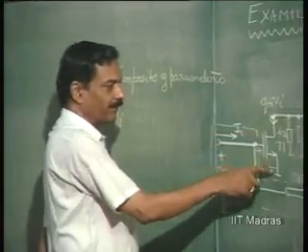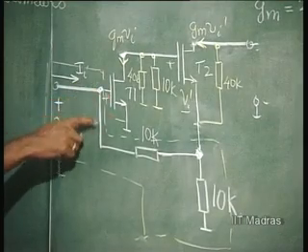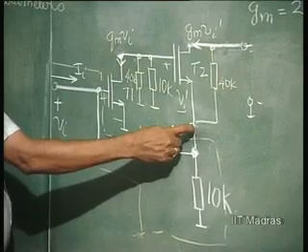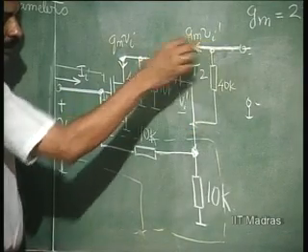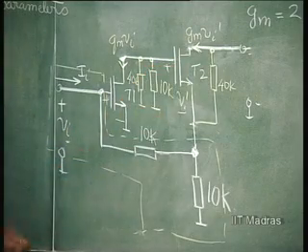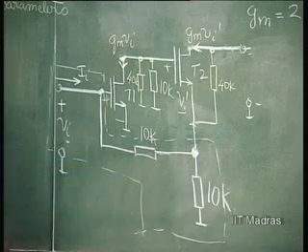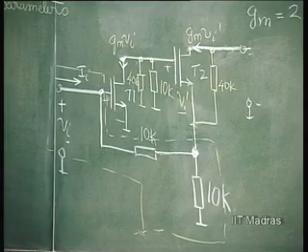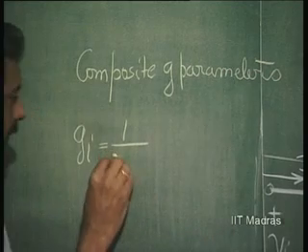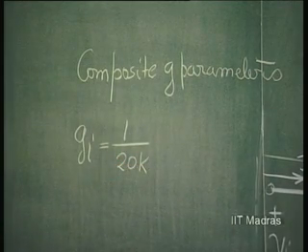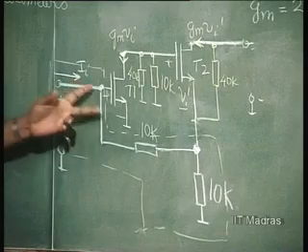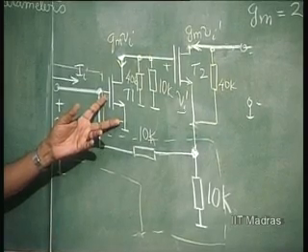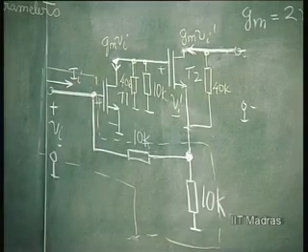Okay. Now, as far as this amplifier is concerned, it is very convenient. There is no current drawn from this. The only current drawn is by this, and this current is 0. If this current is 0, this current is going to be 0. This current is 0, therefore, this current is 0. In this network, this is open because this is a Mosfet here. So, this is open. This current is 0, this current is 0 automatically. So, this resistance that comes is simply equal to Gi is equal to 1 over 10 k plus 10 k, that is 20 k simply. That of the amplifier, okay, Gi of the amplifier is 0. The input conductance of the amplifier is 0, or input impedance is infinity in the case of Mosfet. Otherwise, that would have been added to it.